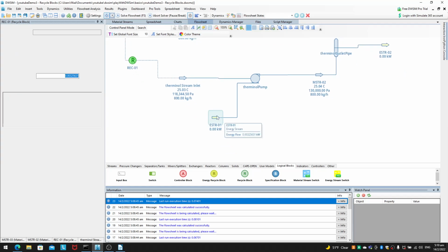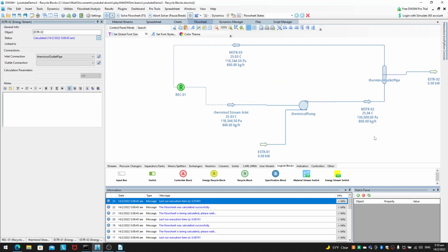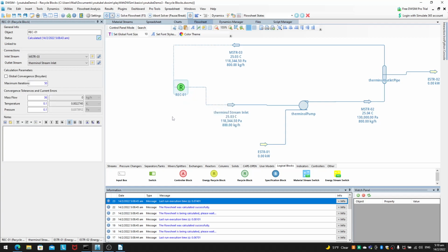Okay, you have to check whether the energy flows in and the energy flows out of this loop are equal. Only when they're equal can you say truly, yes, the flow kind of stabilizes. That's the other physical thing you need to watch: your mass balance, your energy balance. Just now we were talking about energy balance in terms of height, and now we are talking in terms of thermal energy. So you've got to think about these things.